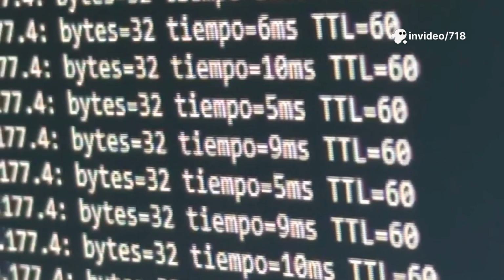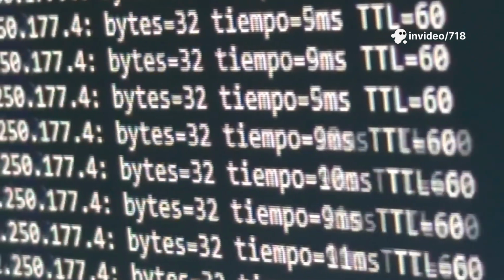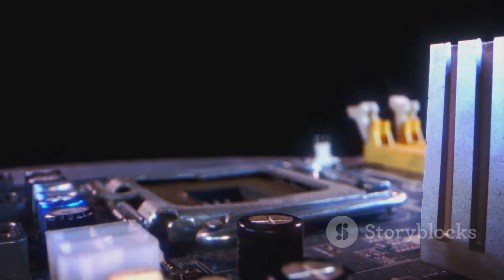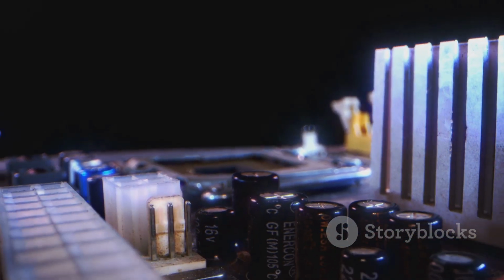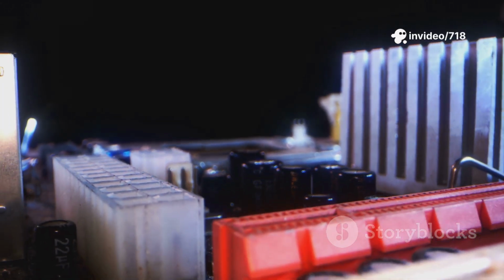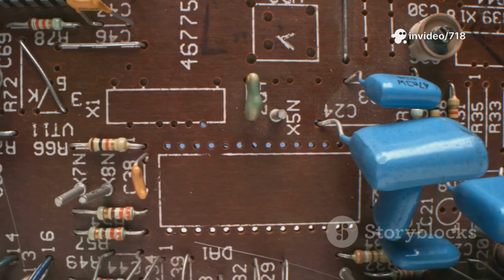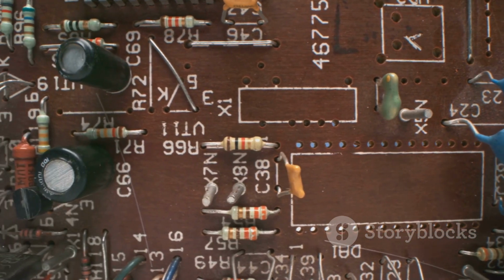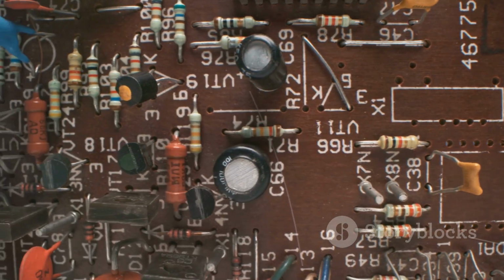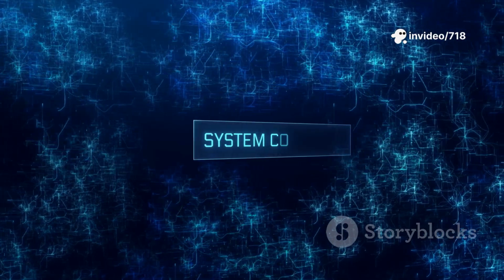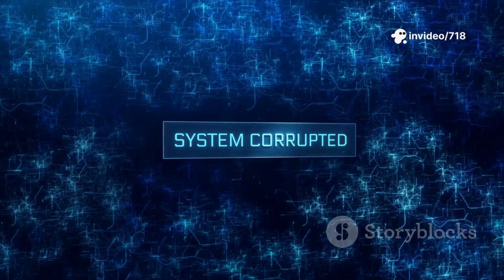Similarly, there's a CAS latency, tCL, which is the time from when you ask for a column to when the data is actually available. These timings, often seen as a series of numbers like 9-9-9-24, are measured in clock cycles and are crucial for stability. These timing parameters are essentially the speed limits of the DRAM. They ensure that there's enough time for electrical signals to travel, for capacitors to charge and discharge, and for sense amplifiers to stabilize. Running timings that are too tight or too aggressive can lead to data corruption and system crashes, because you're trying to read a value before it's truly ready.